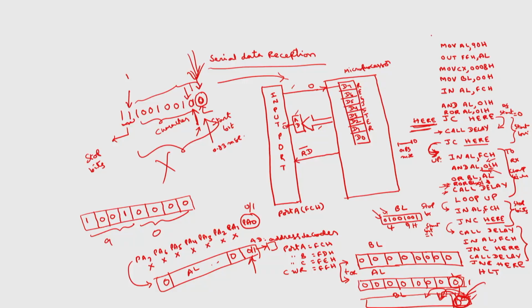Similarly, here also, in order to accept the data at faster rates, instead of using software programs, because with the software program we have to fetch it and execute it, and this will take time. So, instead of that, if you have a dedicated processor, a dedicated interface device, then that can perform these operations, transmission and reception, at faster rates. So, the second approach, instead of software controlled serial data communication, is hardware controlled serial data communication.